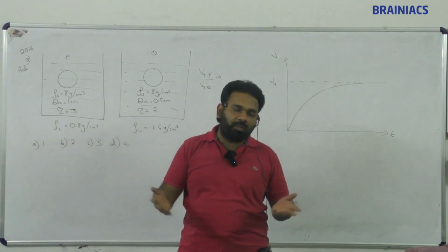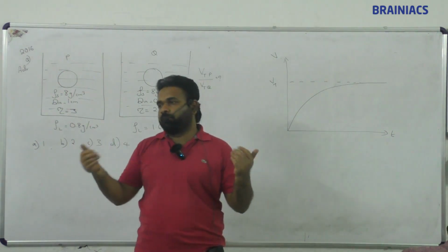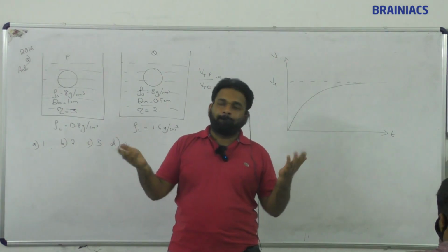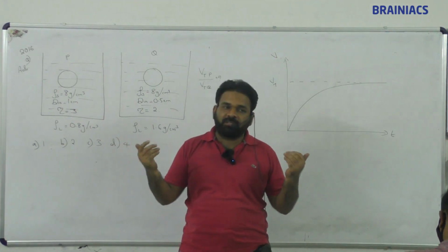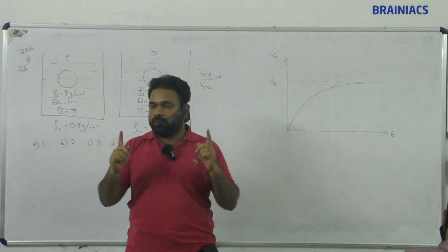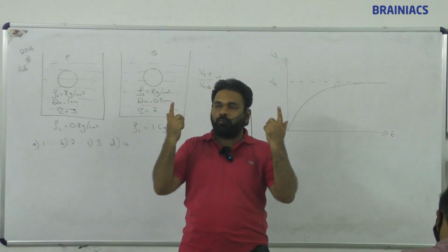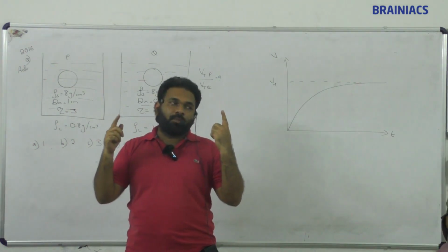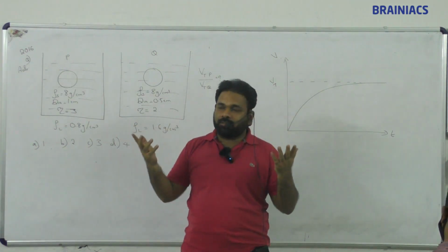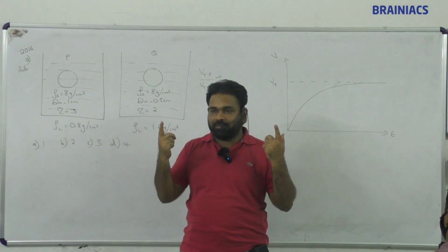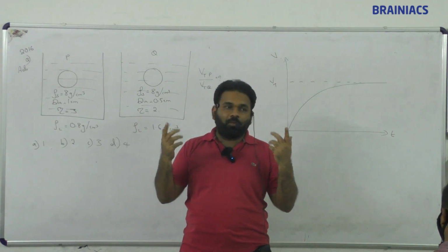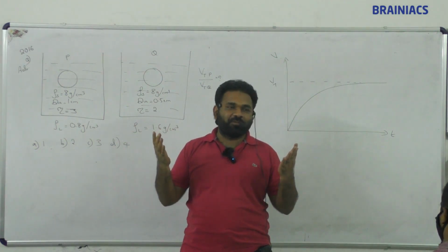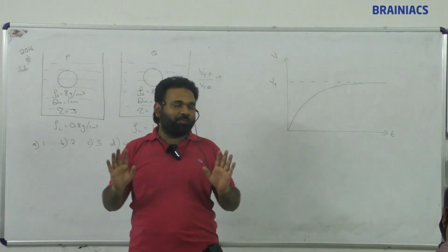Just engage with me. Okay, you start. What is the pressure difference vertically? H rho g. What is the pressure difference horizontally? 0. If it is accelerating upwards, the pressure difference will be H rho g plus a.